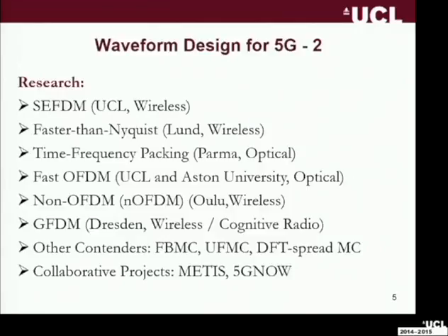Matsumoto, who's Japanese but is affiliated with the University of Oulu in Finland, developed a system toward the end of the 1990s, early 2000s called FOMS, Frequency Overlap Multi-Carrier System, but now he's renamed it NOFDM, which stands for Non-Orthogonal FDM. Gerhard Fettweis, in addition to the tactile internet and the cooperative multi-point systems he's done, is also working on the physical layer at Dresden University, on something called GFDM, which stands for Generalized Frequency Division Multiplexing, and OFDM is a special case of GFDM. So you can probably start to see how all these things come together.